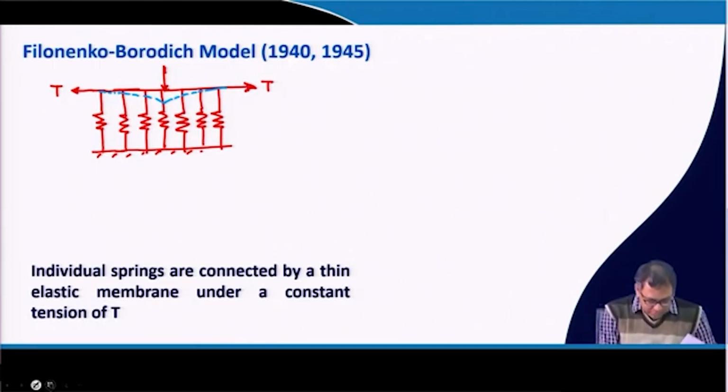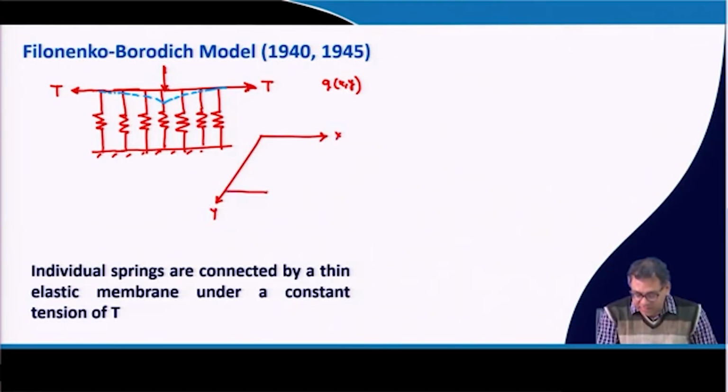Okay. So, now I can give the equation for such a case. Suppose in an xy plane we are applying a stress, suppose this is y, this is x and this is the loaded region. Okay. And below that we have idealized the soil with springs. In such a case, this is equal to k into w.